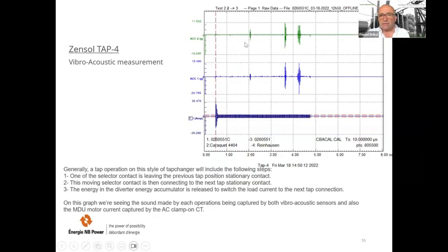And here, of course, the 2 accelerometers, as you can see in the graph, give exactly the same information. So that is why we strongly recommend using only one. And of course, when you do your next test, you absolutely need to go to the same spot.